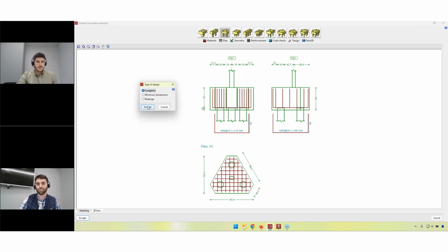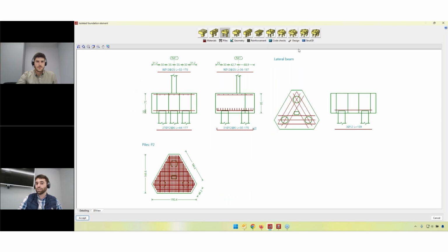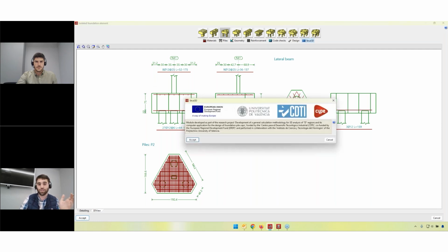for our building site. Also, what is important to mention is this is a type D element, so this is not considered as a beam. The theory of Bernoulli does not apply here, in which you can take the indeformability of the faces. This acts as a very rigid body. So in this case, this has to be calculated with a strut and tie model.